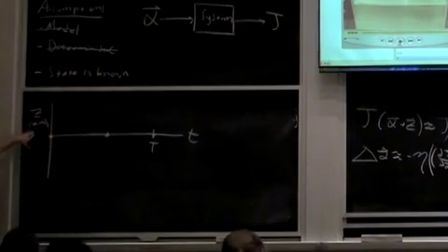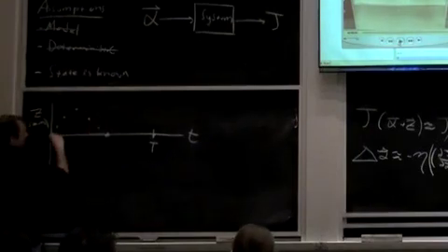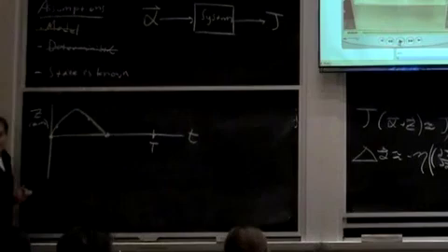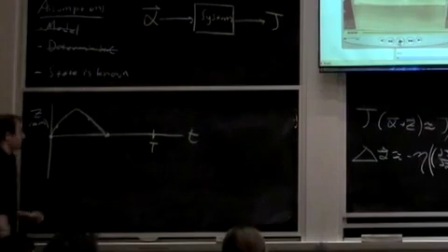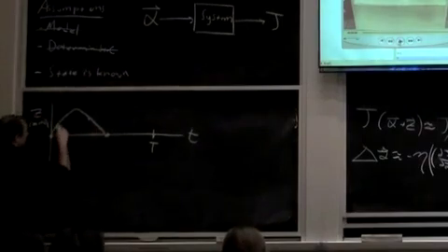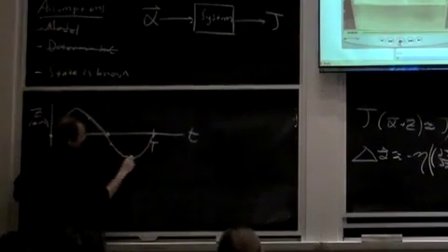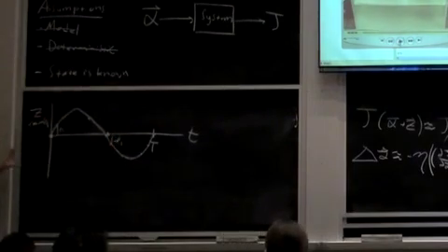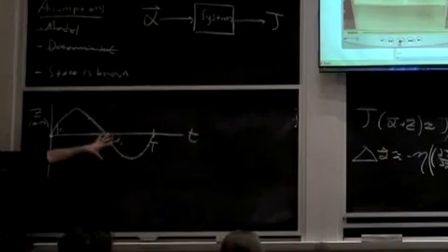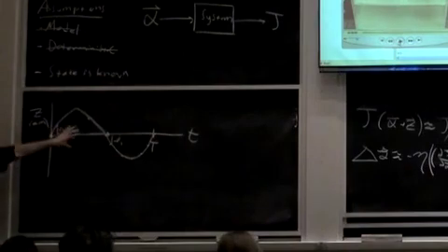All right. So what we do then, we then have 5 parameters. Now we've done several versions, but this is the simple one right here. 5 parameters that define a spline. So this is going to be smooth. You can enforce it to be a periodic spline, which means that the knot at the ends, the connection here, is continuously differentiable as well. And then we force that this parameter, this number P1, is going to be the opposite of it. So this is negative P1. And that's true for all of these. So this way, we have this relatively rich policy class that has sort of the right kind of properties, but we do it with only 5 parameters.